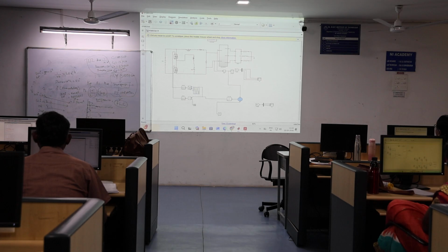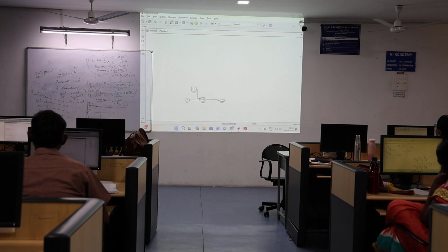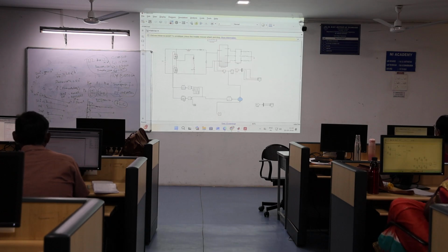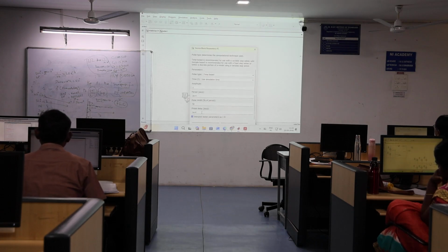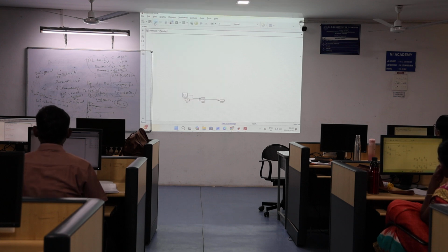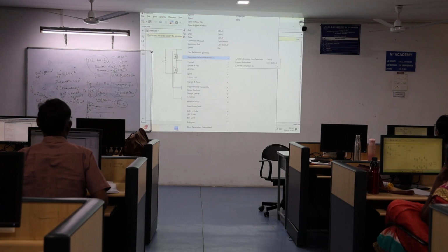I am comparing with my relational operator greater than or equal to, and again I am feeding with the logic of pulse generator I am giving. So while I am giving one with phase delay of 0 and another with phase delay 1e-4, same thing what I gave there. So here when I run this, again if I want to expand, I will give expand.